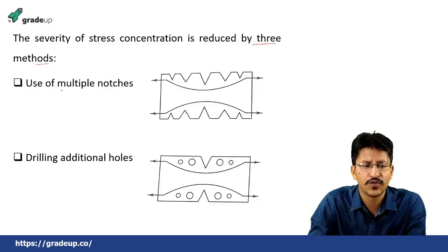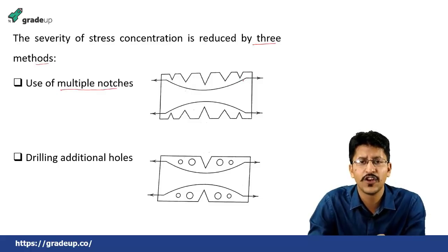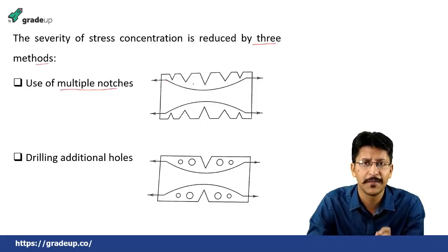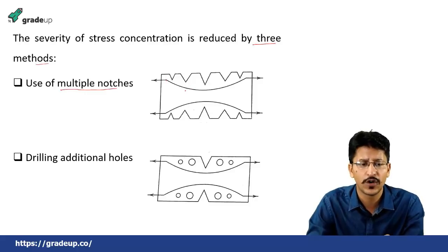The first one is the use of multiple notches. If we use multiple notches, the stress lines will not change abruptly. They will keep on changing slowly and slowly, so the stress concentration will be minimized. I am saying minimized, but it won't be equal to zero.